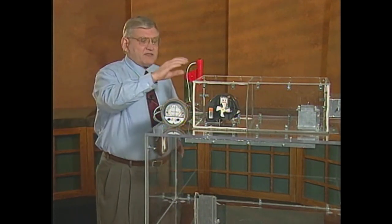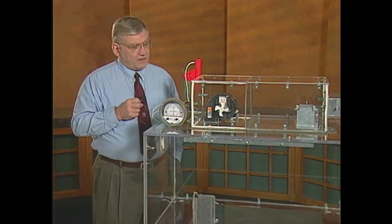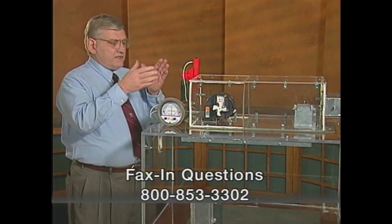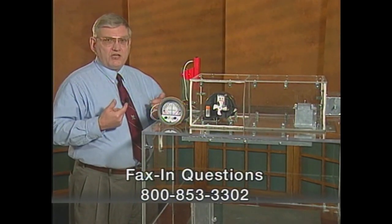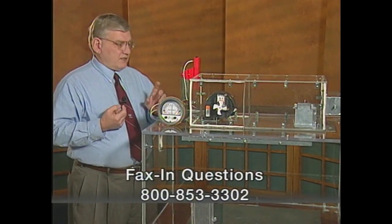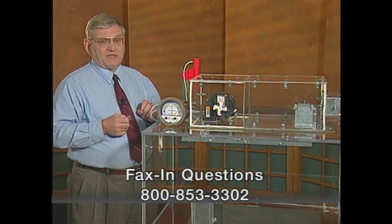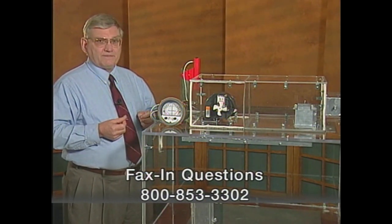The supply fan itself can deliver about 100 CFM, constant volume. The volume of the building is rather small relative to the amount of air that fan can deliver, so the changes that occur in the building relative to static pressure will occur a lot faster than what you'll see in a real building. But we did that for the speed related to this broadcast.